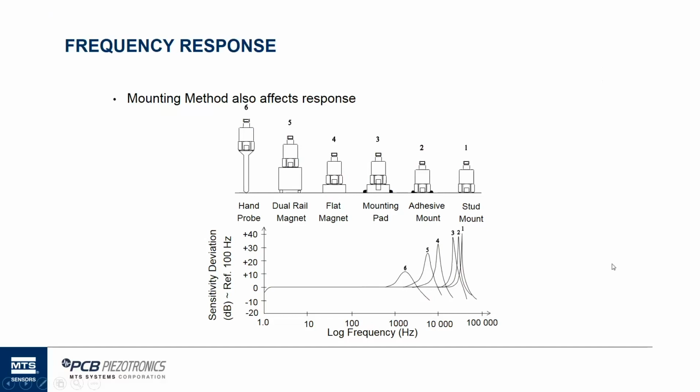But we bring this up from a calibration point of view because there are two kinds of philosophies about calibration when you're calibrating accelerometers. You may want to calibrate it exactly the way it is at the factory to check back to make sure it hasn't changed since that factory calibration, and to determine the sensor health, if you will.